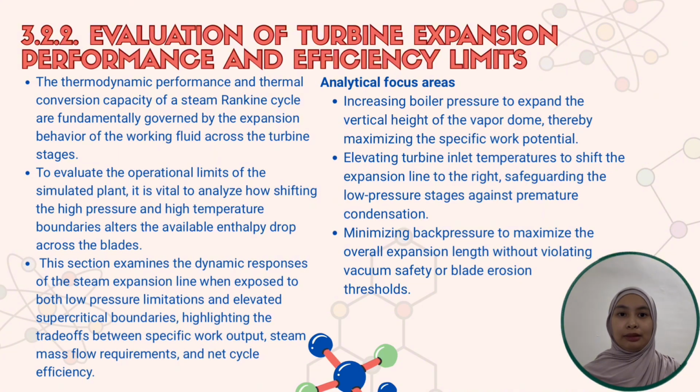In this section, we examine the dynamic responses of the steam expansion line when exposed to both low pressure limitations and elevated supercritical boundaries. Specifically, our analytical focus areas center on 3 tactics: increasing boiler pressure to maximize specific work potential, elevating turbine inlet temperatures to safeguard lower pressure stages against premature condensation, and minimizing back pressure to maximize overall expansion length without violating vacuum safety or blade erosion thresholds.